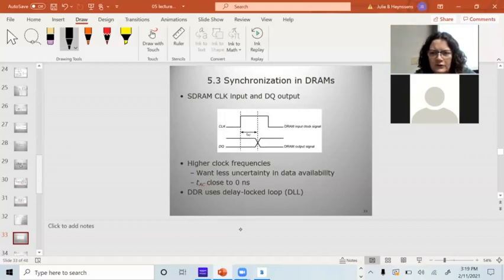After the clock edge and you ask for the data out, it takes some amount of time for the data to change. This is when the signal's valid after that clock. If you have higher clock frequencies, the amount of time you have for your data to settle goes down. So all your circuitry has to get faster.